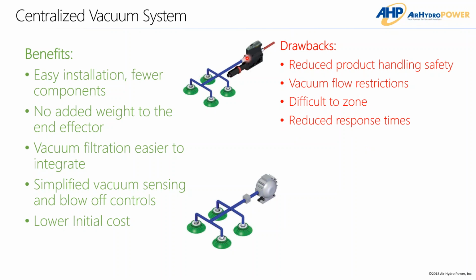Reduced response time. So if you just think about how in this case with the compressed air driven, you still have the time of reaction from wherever this pump is located to pull a vacuum through all of these cups in order to evacuate all of this volume before you're getting to that peak vacuum. And especially with the blower pumps, since these usually have to be running all the time in order to be able to react quick enough in the process, you still have to evacuate all this line to be able to pull your peak vacuum on your system.